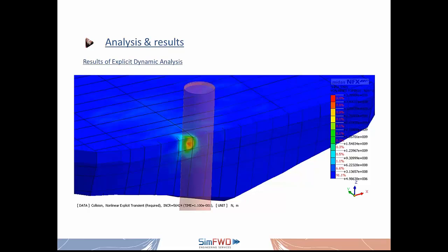And here you can see some initial results coming from this impact, which are also stored into the same model database, and we now effectively have a full analysis cycle starting from the CFD part, going to the structural linear static, and then following with the collision impact analysis at the end, and all within the same platforms, utilizing the same models and getting the results also in one database, being able to plot them